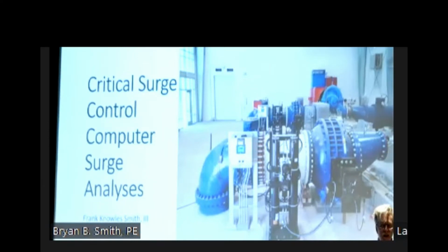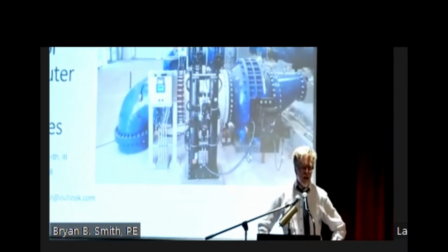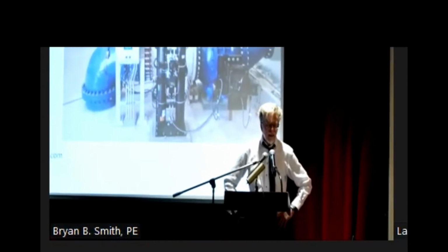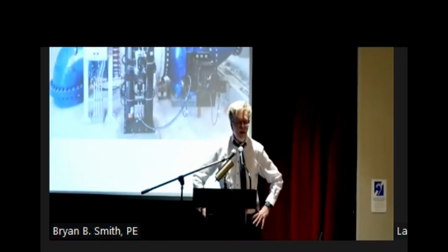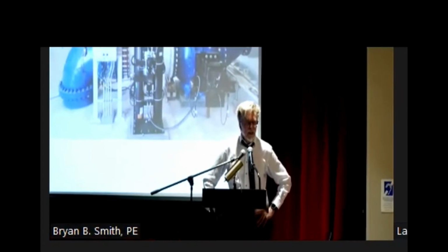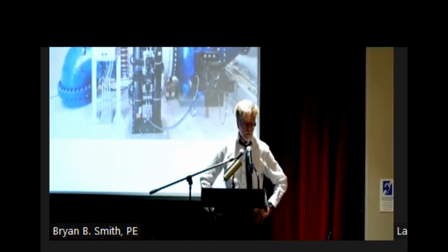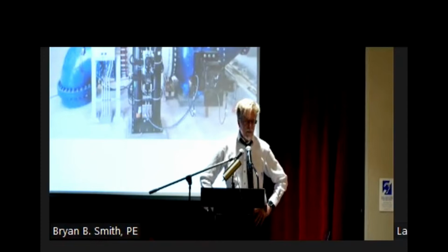So there's certain areas. How do you solve a problem like this? Don't weld the manway cover to the street, because that pressure surge is going to destroy your whole road with that upsurge in pressure. In some cases, we look at this and try to model it, but we can't model it because this is a two-phase flow.